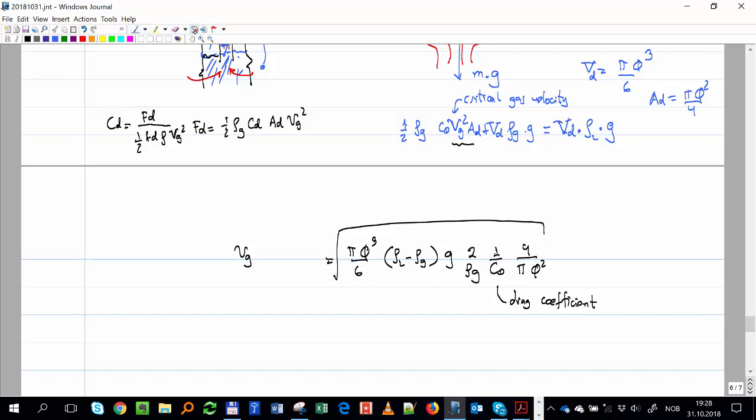It's a dimensionless number. But we are not going to go too much into that. Just saying that you can express that force for a sphere, assuming it's exactly a sphere, like that. And because the velocity of the gas is also very high, you can say this is going to be a constant, 0.44, because you are in the turbulent regime.